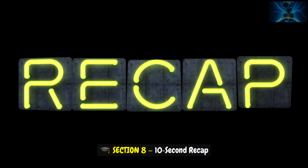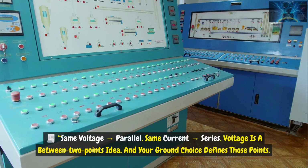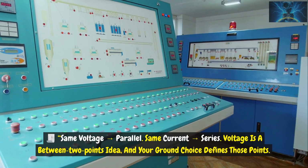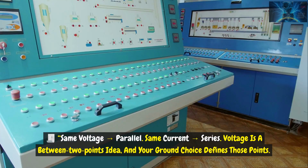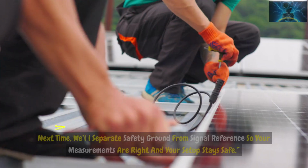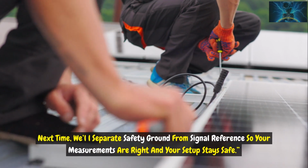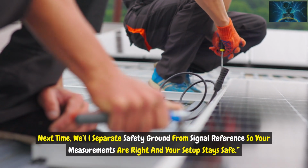Section 8. 10-second recap. Same voltage, parallel. Same current, series. Voltage is a between 2 points idea, and your ground choice defines those points. Next time, we'll separate safety ground from signal reference so your measurements are right and your setup stays safe.